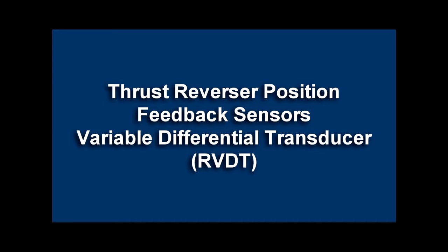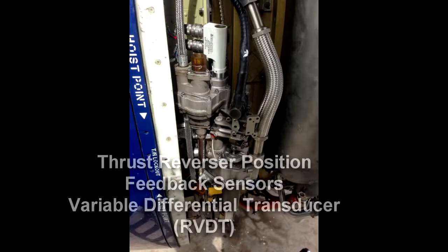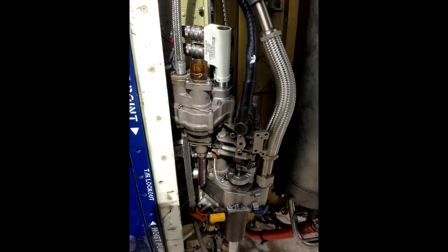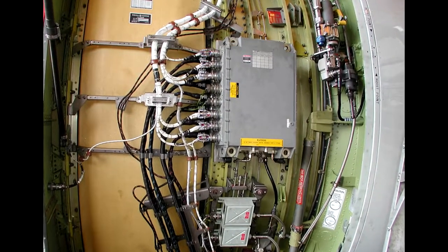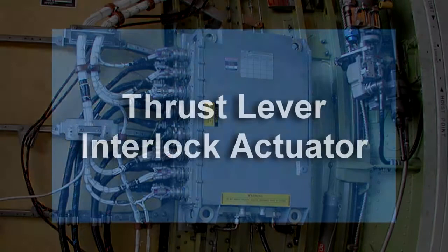Rotary variable differential transducers, RVDTs. The RVDTs, or transducers, have dual feedback channels. Each thrust reverser center drive unit, CDU, has an RVDT, or transducer, attached. The purpose of the RVDT is to give the reverser position to the electronic engine control, EEC. In turn, the EEC commands the thrust reverser interlocks to ensure there is correct sequencing of engine power in relationship to the thrust reverser position.